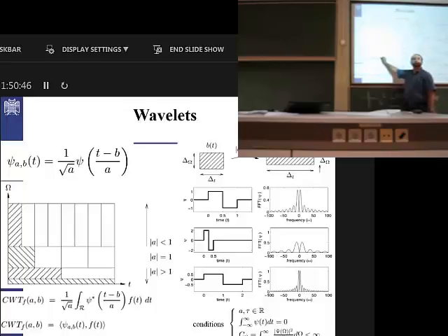Then you chop the window into two. You get this information for the frequency part. It's not frequency, it's just scale. You remove that and you save it, and that's all. You never come back to this again. And so on and so forth, we go further for all the parts. In the same way, we have again the same area, but this area is dynamically changing. So we have the resolution over time and frequency. Sometimes you compress it or stretch it, based on whether you need the time resolution or the frequency resolution.